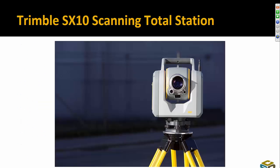Okay, a lot of the scanning capability has gone into TBC over the last year and a half to prepare the software to run with the new Trimble SX10 scanning total station. So if you haven't seen this instrument, this is the latest total station from Trimble, and it's basically a 1-second total station combined with a 3D laser scanner that can shoot 26,000 points per second. So a huge upgrade over the pseudo scanning capability of the S series total stations.